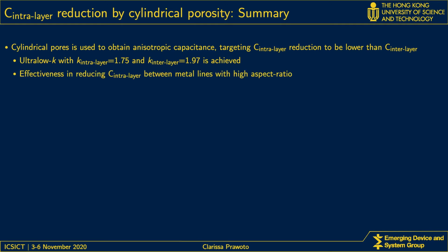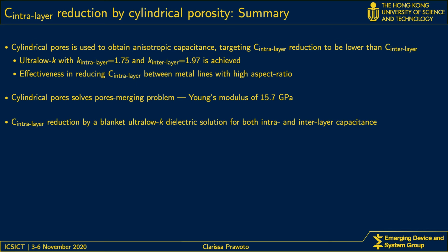Then we have evaluated the application in delay reduction, and at the same time, the proposed porous dielectric structure is mechanically stable. What it means is that this approach can be used as a blanket ultra-low-K dielectric for both intra and interlayer levels, and it is intrinsically more effective in lowering the intralayer capacitance.